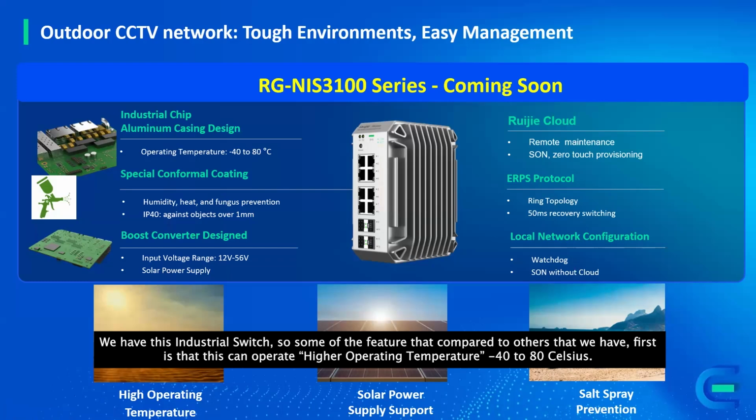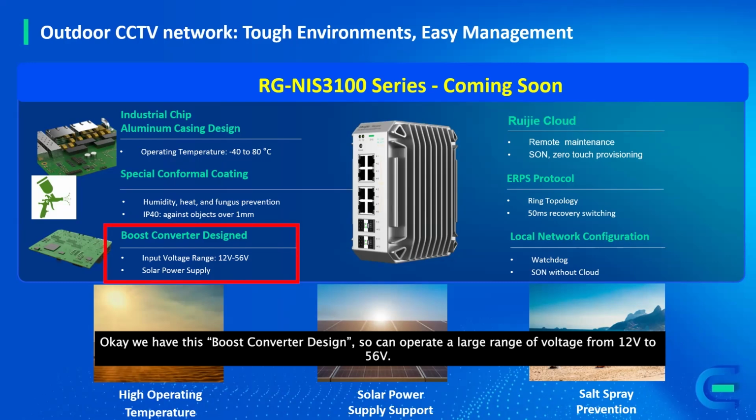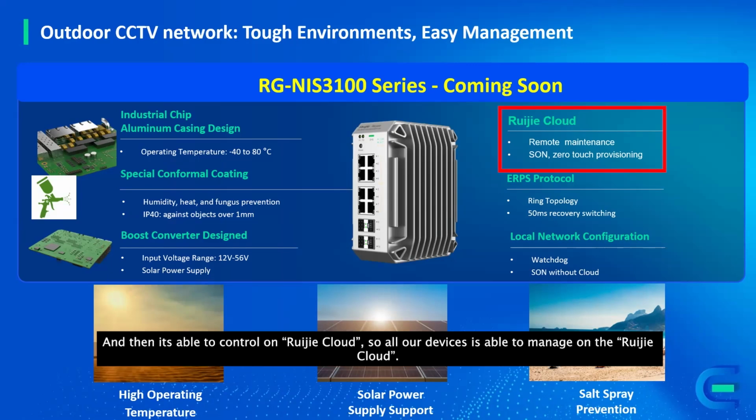Some of the features compared to others: first, this can operate in a larger range of operating temperatures, from -40 to about 80 degrees. The IP rating is IP40, which means it is dust proof, so any dust or even small ants are unable to go inside these switches. We have a boost converter design, so it can operate on a large range of voltage from 12 volt to 56 volt. Normally we use a solar power supply, which can have a 12 volt output, so we can connect directly to it, and it is able to be controlled on Ruijie cloud. All our devices are able to be managed on our Ruijie cloud.